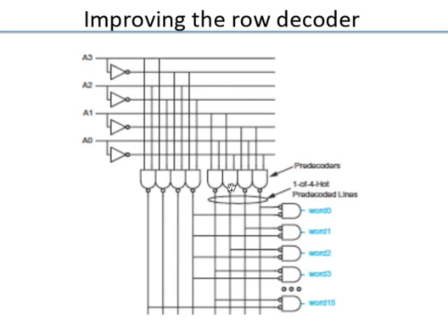With this 2 to 4 decoder, one of these 4 lines becomes active, and with this 2 to 4, one of these 4 lines becomes active. And now you can combine one each from each group. So again you have 16 possibilities, all 16 are set up here. So this technique is called pre-decoding. Pre-decoding has the advantage, it turns out again to be the better way of doing decoding, where you can get faster decoders and lower power decoders.